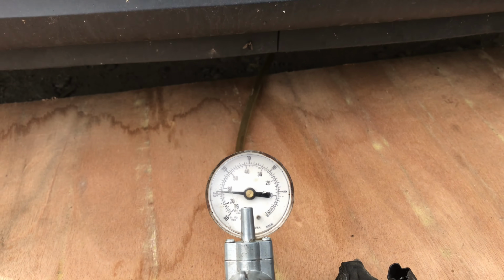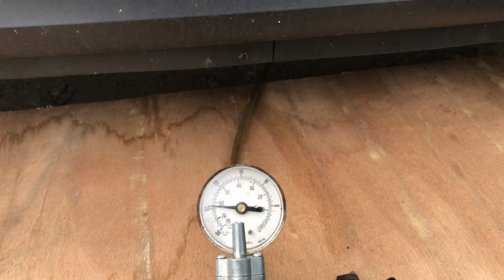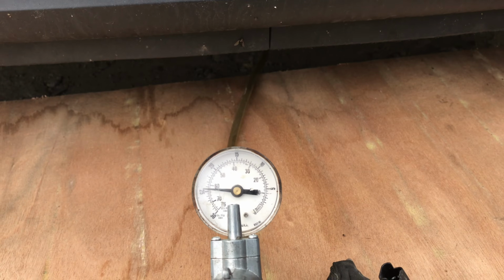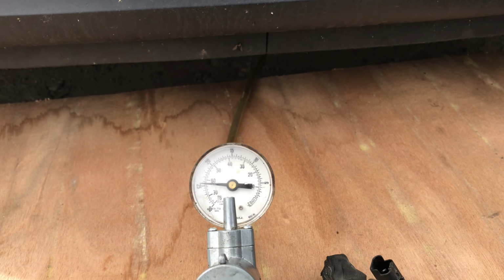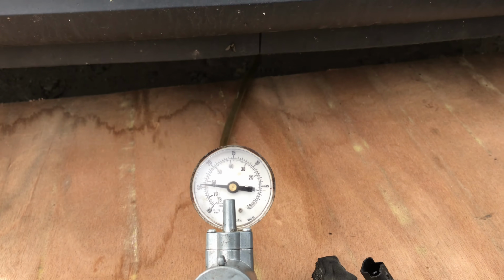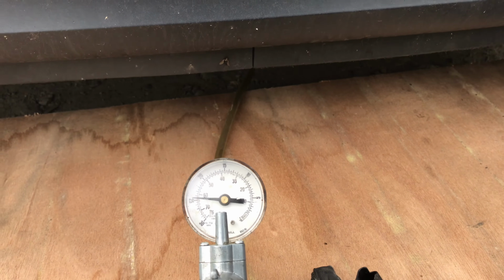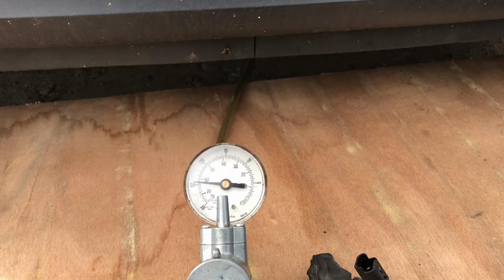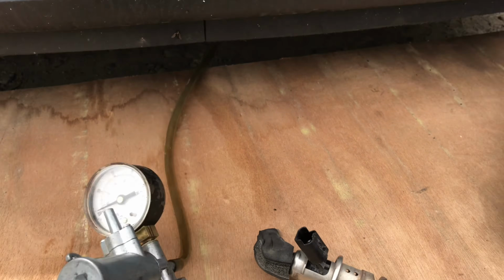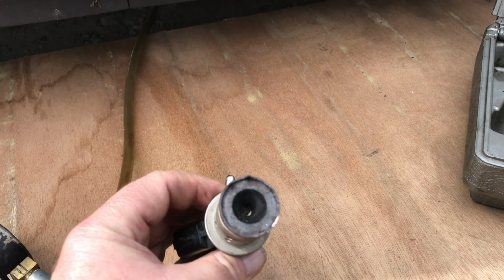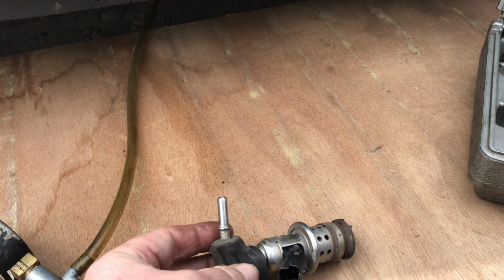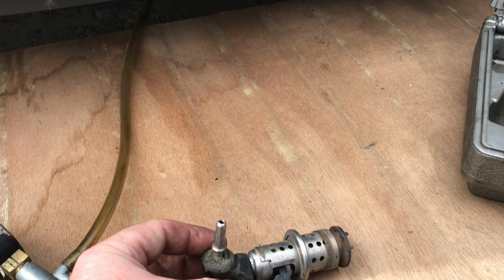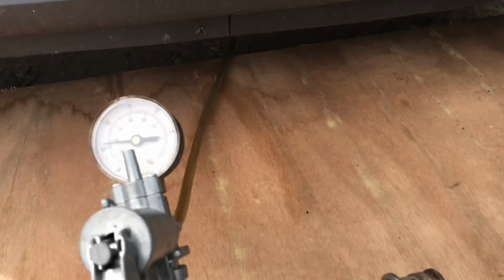So that says to me all the way from the injector, all the way back to the tank, that pipework is good. And I kind of suspected that when I was seeing 4 bar of pressure. And it was eventually getting up to 5, but we're now at the stage we can't even get it to build pressure. With the new injector installed, because this is the old one, we put a new one in, we can't even build pressure anymore. And we've told the computer it's got a new injector, and it ain't working.